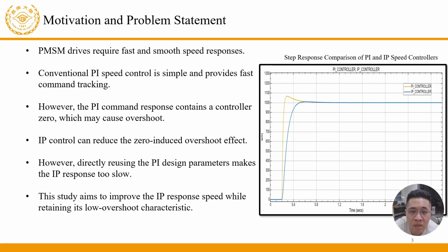PMSM drives are widely used in applications that require high efficiency and fast dynamic response. For speed control, the conventional PI controller is still widely used because it is simple and easy to implement. However, the PI speed controller has one important issue. Its closed-loop response contains a controller zero. This zero can make the response faster, but it may also cause overshoot